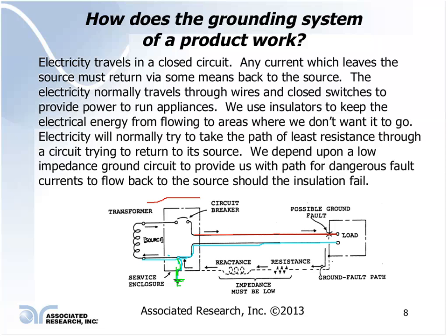Okay. If this were in the home, like my parents' house, and this was our refrigerator, and it did not have the ground circuit, you could have enough leakage current flowing in that product that this leakage current would flow through whatever insulation resistance, capacitance and so on, to the frame of the refrigerator, and as soon as you came in contact with this metal enclosure of the refrigerator and ground, you could receive an electrical shock even if there wasn't a fault within the appliance itself. This product could continue to operate.